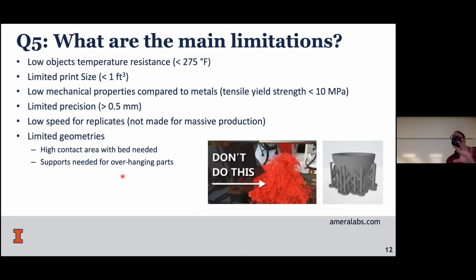You can always change the parameters you print with. So let's say you design an item, what's inside you can decide to put full of filament, or then there's a certain infill where 10% of the area is filled, or 50% is filled. So by playing with these parameters, you can have better mechanical properties.